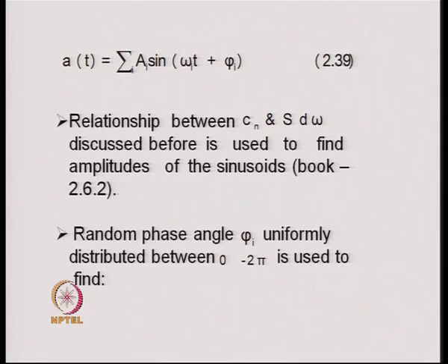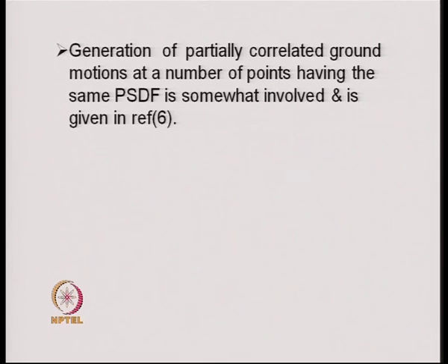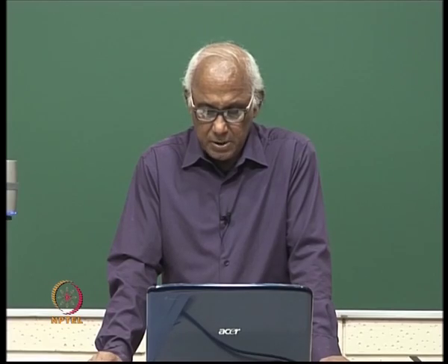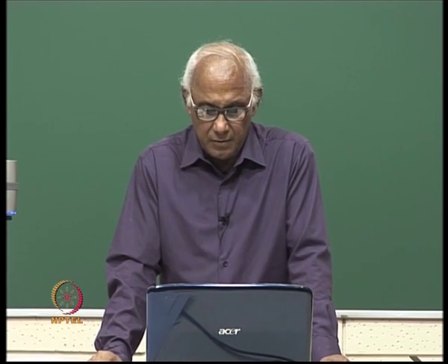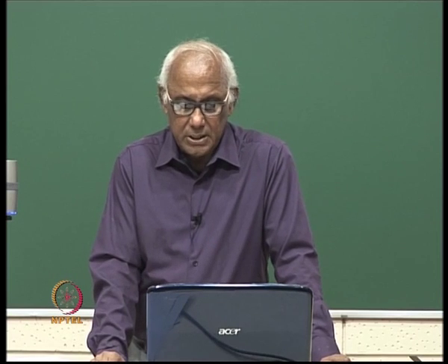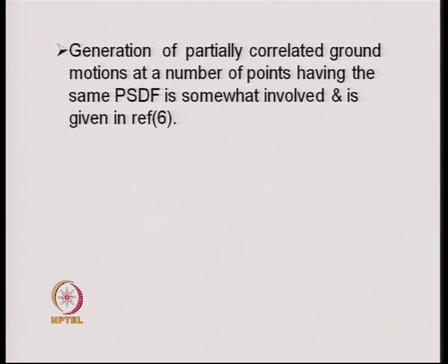Many standard programs are these days available in order to obtain the time history of ground motion which are compatible with the power spectral density function or a given response spectrum. Generation of the partially correlated ground motion at a number of points having the same PSDF is somewhat involved, and however, the methodology is given in reference 6 of the book.